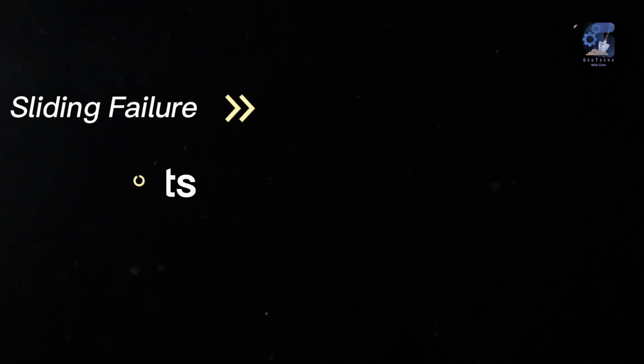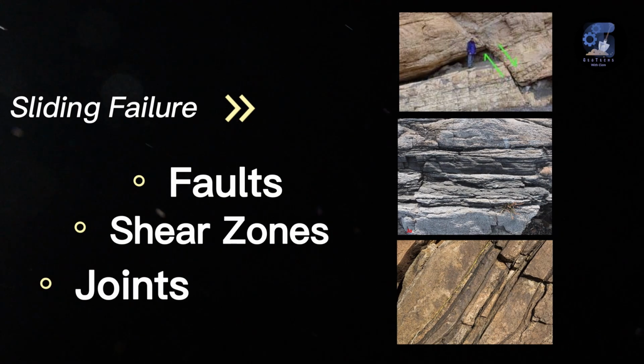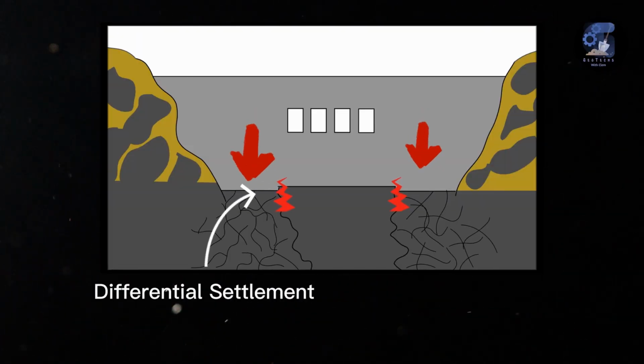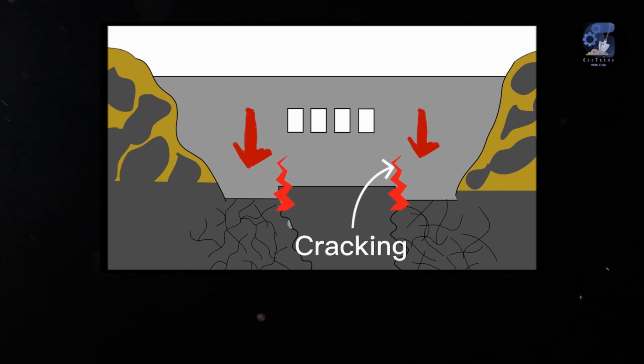The foundation or portions of it must be analyzed for stability whenever the structural configuration of the rock is such that direct shear failure is possible, or whenever a sliding failure is possible along the faults, shears, and joints. Associated with stability are problems of local overstressing in the dam due to the foundation deficiencies. The presence of such weak zones can cause problems under either of two conditions: when differential displacement of the rock blocks occurs on either side of the weak zones, and when the width of the weak zone represents an excessive span for the dam to bridge over.